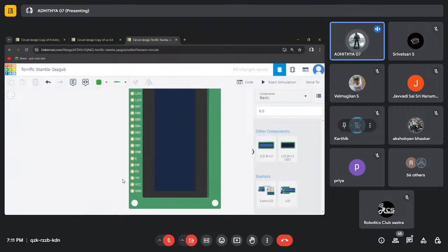We'll be connecting the third, middle pin of the potentiometer to the V naught so that we can control the right contrast of the display. And then VCC and ground, which are usual, are there to power the whole thing.